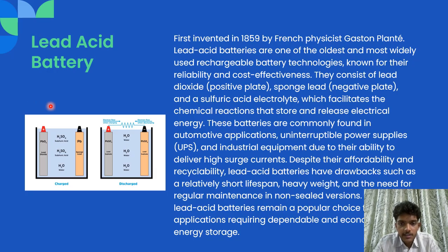Despite their affordability and recyclability, they have a lot of drawbacks, such as relatively short lifespan, heavy weight, and the need for regular maintenance in non-sealed versions. The sealed version of a lead acid battery is known as SMF cell, which we'll come to later in today's presentation. Lead acid batteries remain a popular choice for applications requiring dependable and economical energy storage.